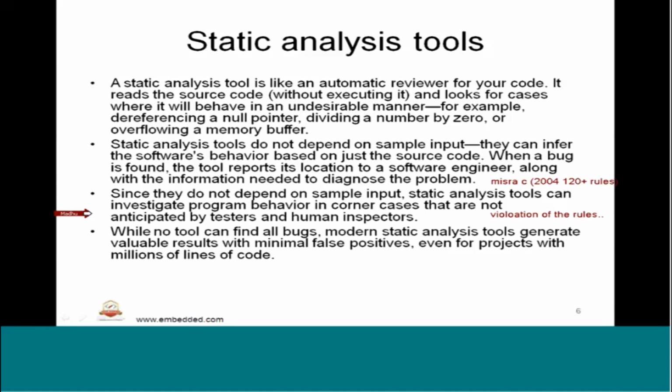Those things can definitely be caught with the help of static analysis tools, because for that the programmer dependency or the sample input is not required. By simply inferring the program flow or the data flow of the embedded software, the tool will identify such issues which are hiding from the human while doing the inspection.